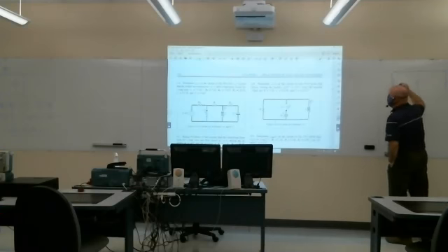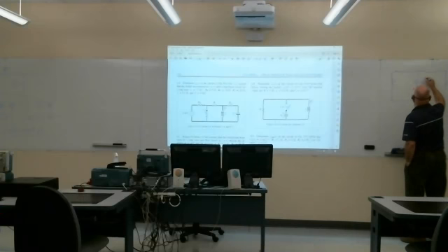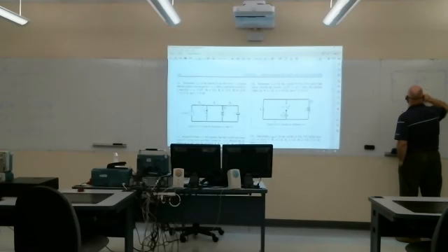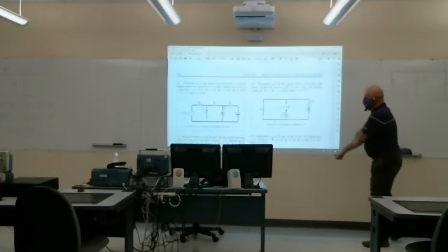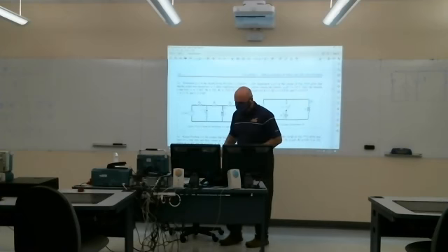R is 1, L is 0.8, C is 0.25, so that would be 4 over S. And we need to find this current. Let's do it with a current source in parallel, and that 24 volts across that capacitor initially.